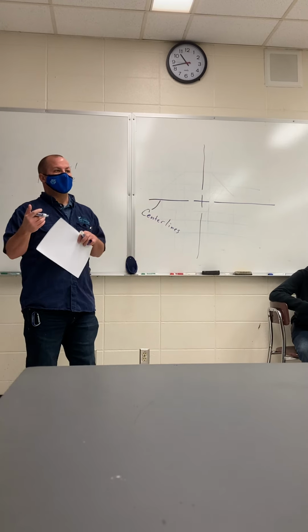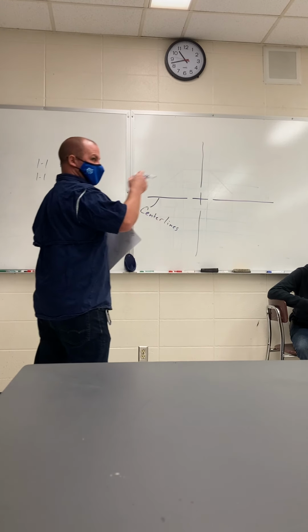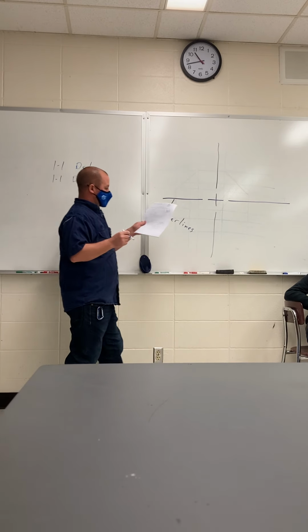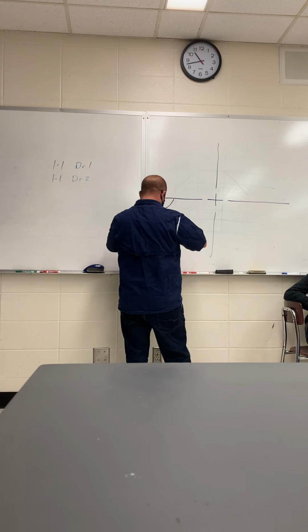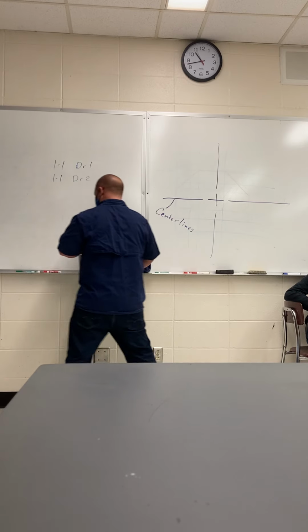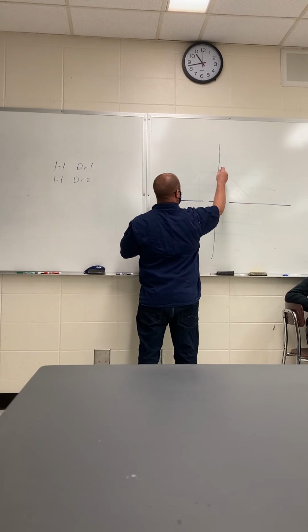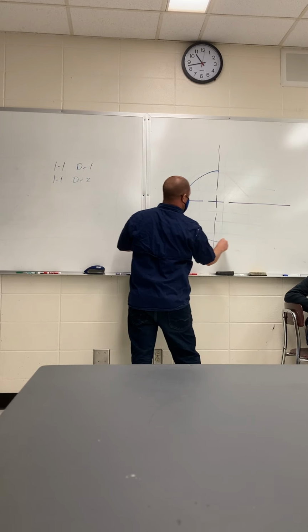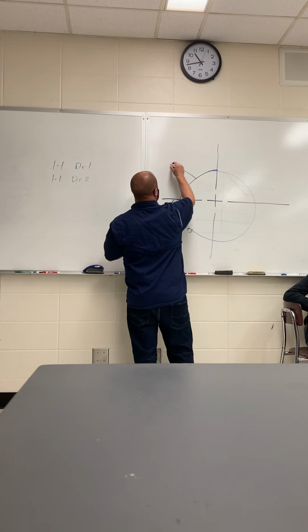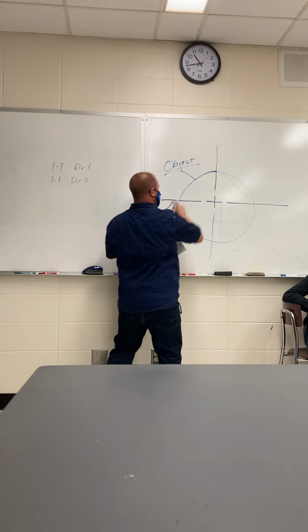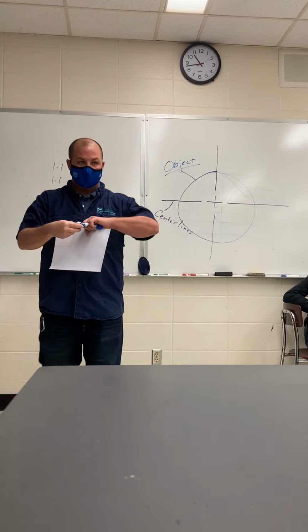Everything that you've done up till now has been what we call object lines. So like the outer extents, or when we draw this circle, when you actually physically draw this circle, that's an object line. And I'm going to get into the difference and how to set them in AutoCAD.